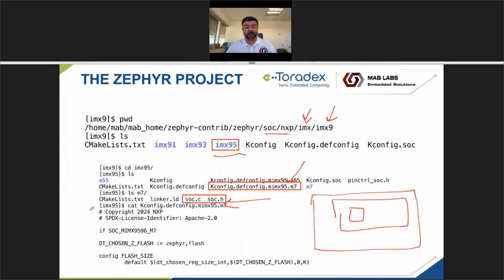And then if we look at the Kconfig right here, we can see that this is the link between the device tree and the Kconfig and then eventually the source code. So if you have any sort of background in Linux, the device tree is managed at runtime, right? Linux looks through the device tree, identifies what devices need to be enabled, and goes through the process of calling the appropriate functions to initialize the hardware that the device tree has told it about.